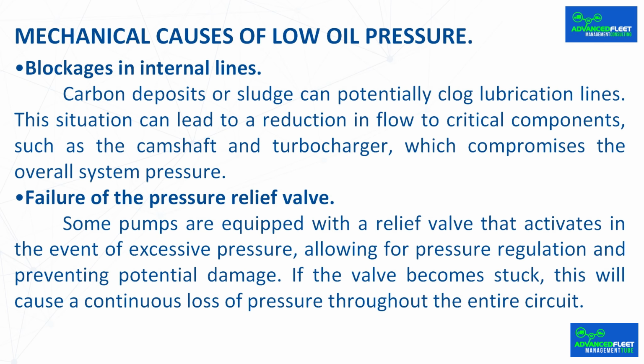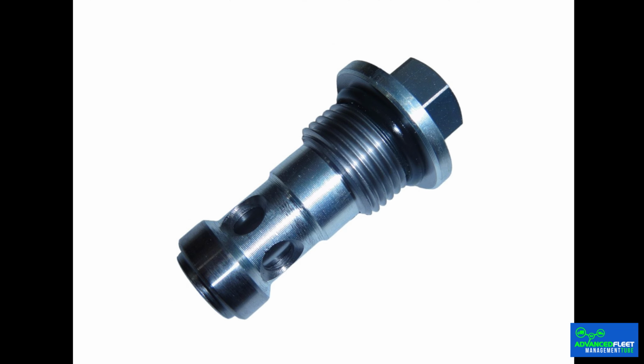Blockages in internal lines. Carbon deposits or sludge can potentially clog lubrication lines. This situation can lead to a reduction in flow to critical components, such as the camshaft and turbocharger, which compromises the overall system pressure.